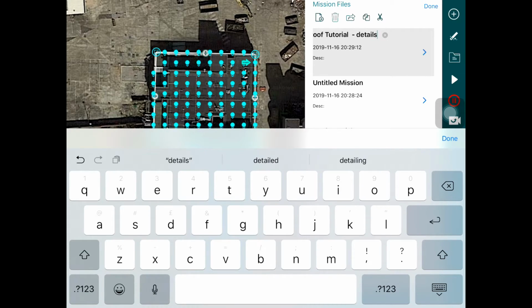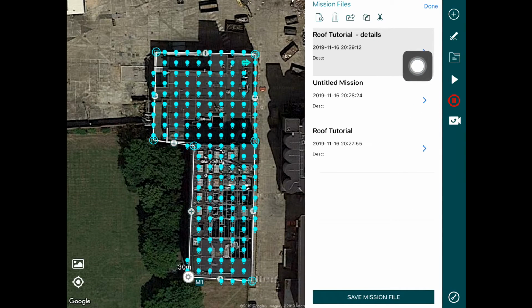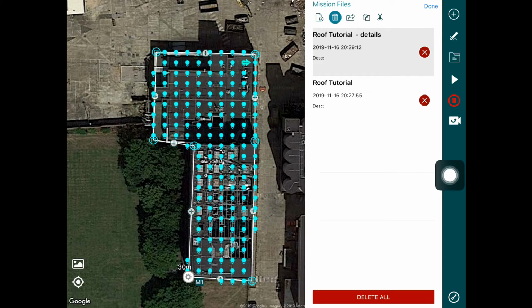So you've got 2 missions configured now on the same area, and let's get rid of the middle mission because we don't really need it now. So I'm just gonna hit the bin or the trash can, as you might want to call it, depending on where you listen to this from. You can basically click on that and you'll have all these bin icons that appear in the cross icons, and you can essentially just click on one and then you delete a mission.